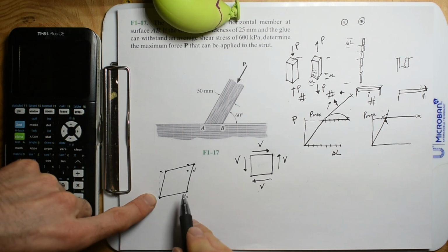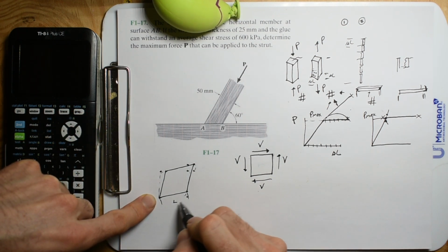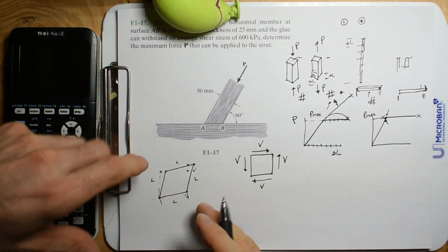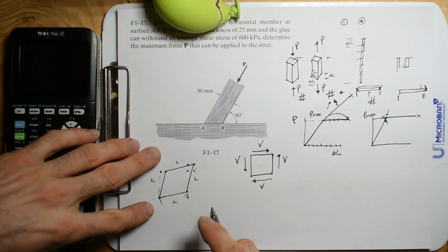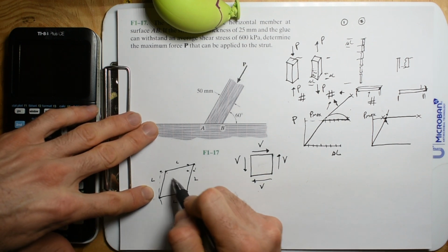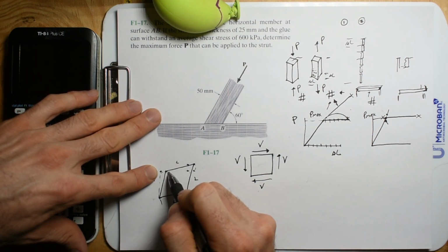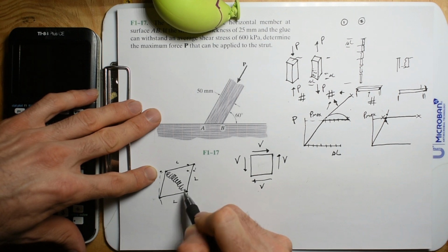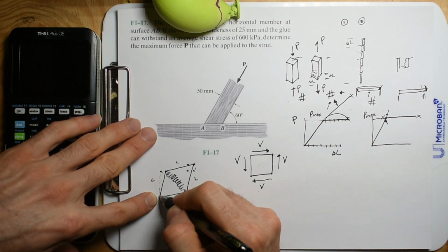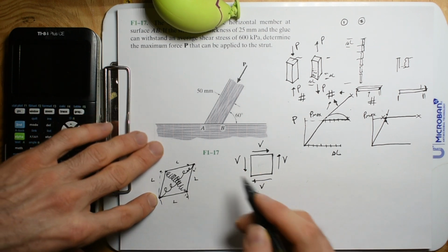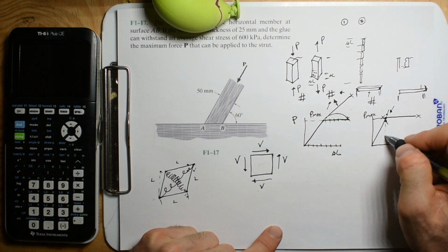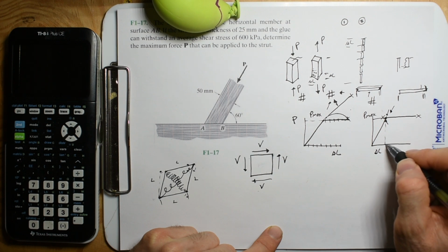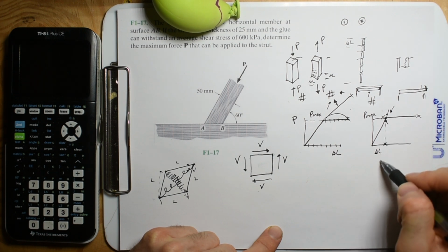And then what happens with this is that these lengths stay the same. We have no change in length of this. But you get a compression from here to here. Like this compresses. And then you get a lengthening from here to here. This lengthens. And one of the aspects I pointed out in material mechanics is that if something changes in length, it gets to a point where it can only change in length so much, and then it breaks.